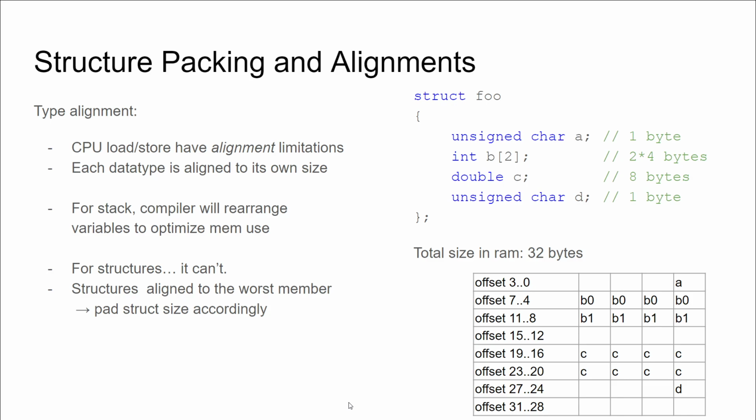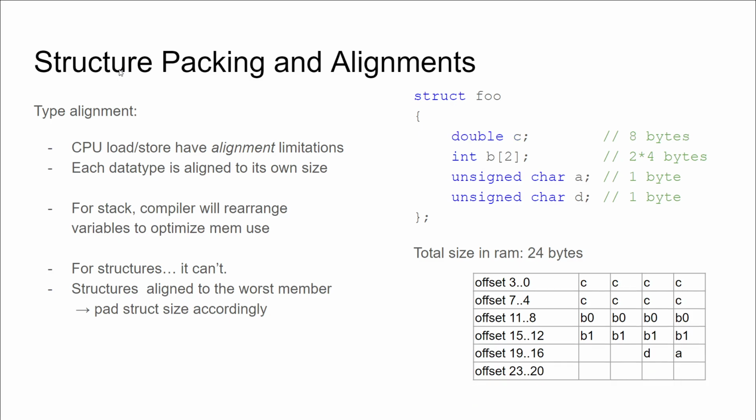That's substantial. It would be easier if we could rewrite the data structure and reorder their appearance. And if you're just adding variables on a local stack in C, the compiler will certainly do so, but for a data structure it can't, because that data structure is an interface. The interfaces need to work across multiple program modules, so you need to ensure that they're in the same order in every module. So if we rearrange them a little bit ourselves, we can certainly cut down on the memory size of this data structure. Here's a minimal set.